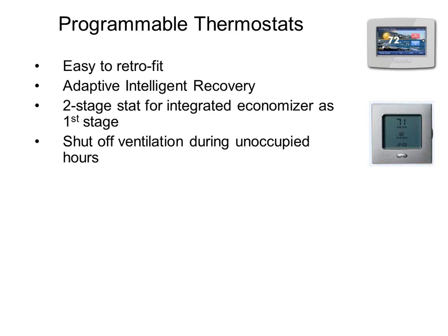Well, the ventilation damper is simply tied to the fan. Whenever the fan is on, the ventilation damper goes to minimum ventilation position and brings in 15, 20, 25, 30% outside air, whatever was required by code. There's no reason to do this. You only have to ventilate a building for code if there's people occupied in the building. If there's no people there, you don't have to open the damper. So really, you want the damper to be shut.